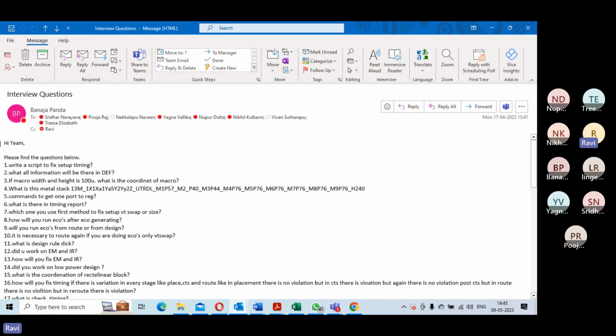Uniquify, sort out all that stuff. Sort all the cells whose delay, if you search that delay column, if it is greater than 40 picosecond, you capture them and collect all those cells, sort them off, uniquify them, and whichever is more than 200 picosecond, you can actually upsize to, let's say if it is 1x, then you can upsize to 4x driver.